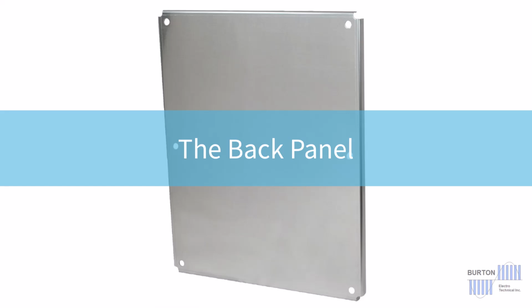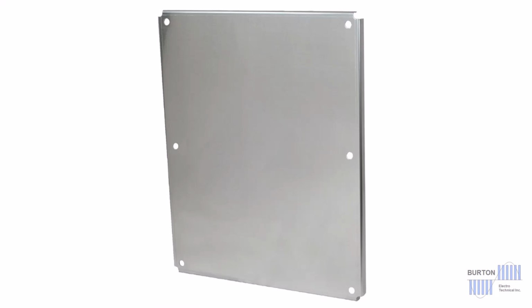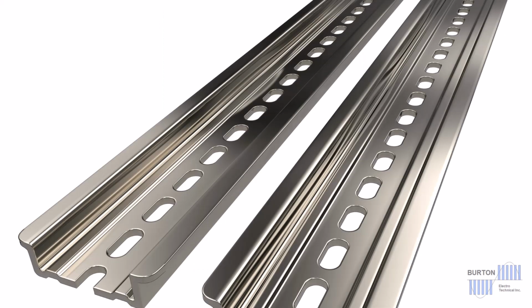The back panel. The back panel is mounted into the enclosure. Its job is to provide a mounting surface for the electrical power and control devices. Mounting rails are installed to allow devices to be easily secured and positioned. These rails are called DIN rails.